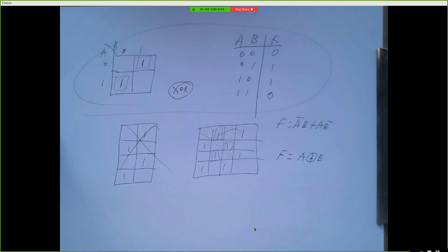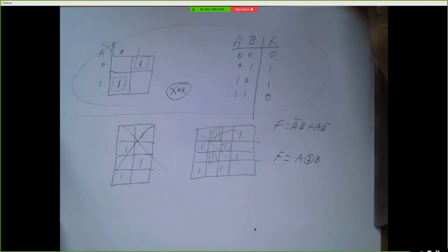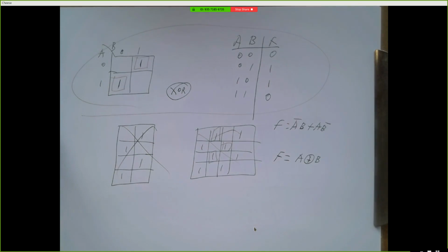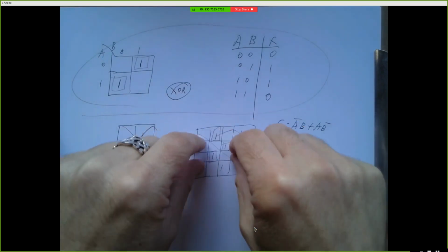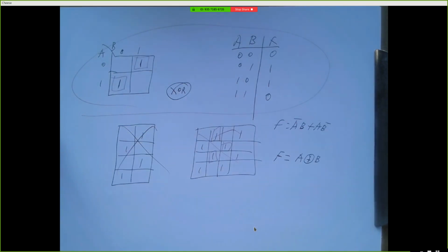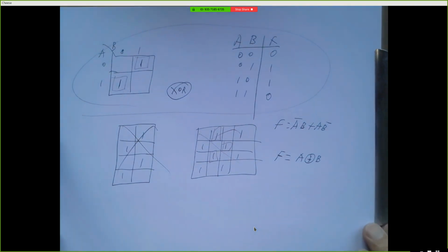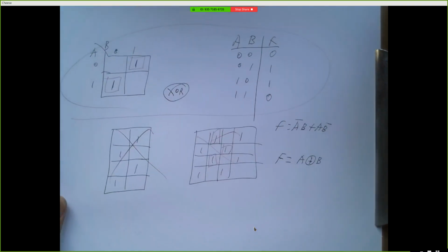So we'll come back to looking at exclusive ORs in a couple of labs when we talk about adding circuits, circuits that do addition, and what it means to XOR 3 variables, because it's not really a 3-input XOR, but there's a way we can define XOR of 3 or 4 things, and it corresponds to these checkerboard patterns. So when you're designing circuitry and you're coming up with K-maps that have these small rectangles, there's a possibility you can use an XOR to get a simpler circuit. So we'll dig more into that as it comes up.